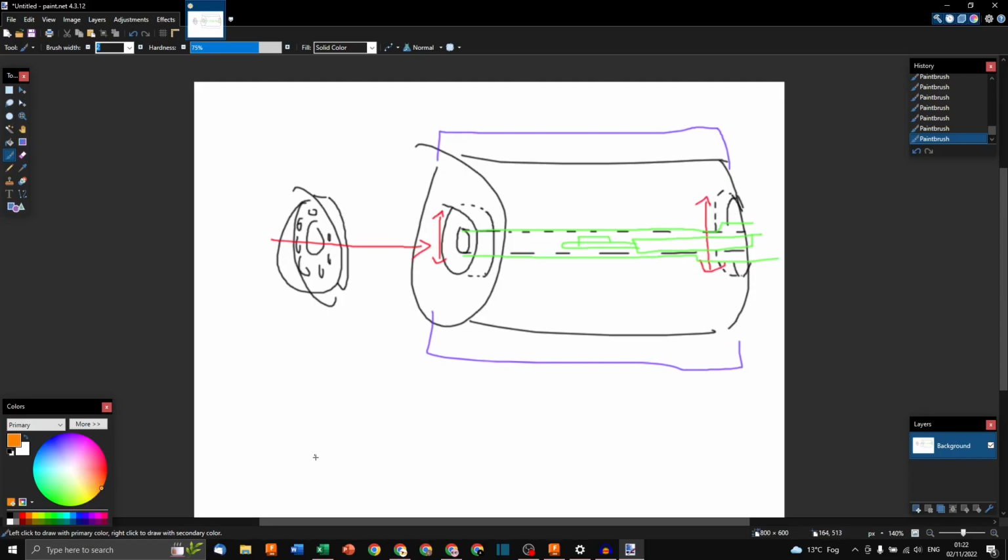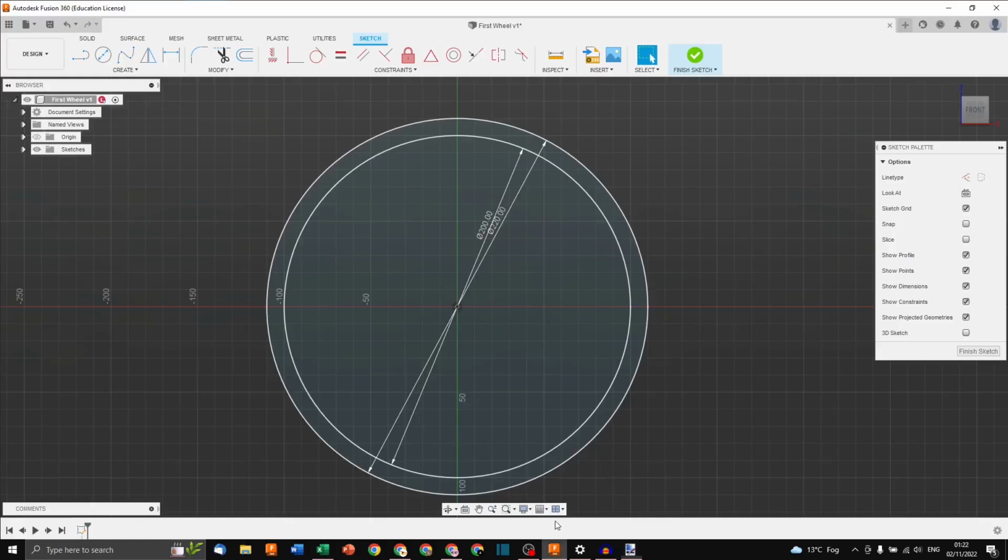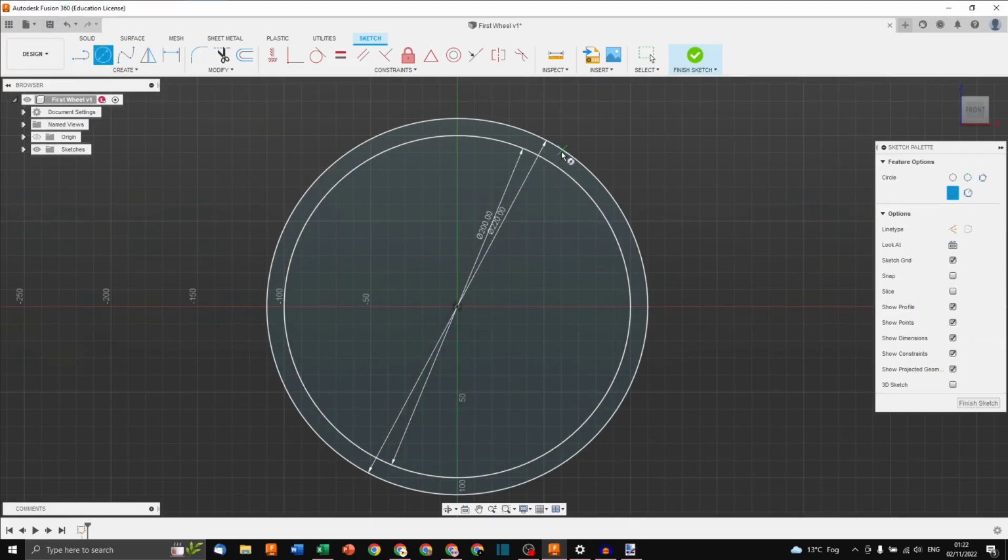So we're only going to be sketching this face, and we'll have the inner bore, ID, this one. We'll have the small bearing seat, the big bearing seats, small, big, then outer diameter of the wheel, then in purple, the tire. And then you'll see how we'll do to extrude all of these circles, all made on one single plane here, into all these different features. I think it's the best way to learn the extrude option. So, as we were saying, this is for the tire, this is for the wheel.